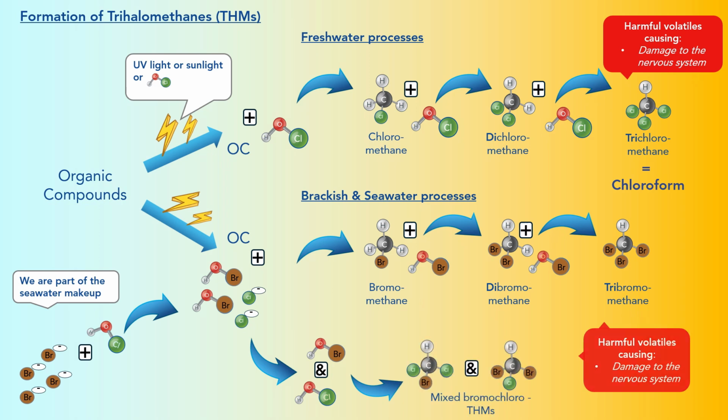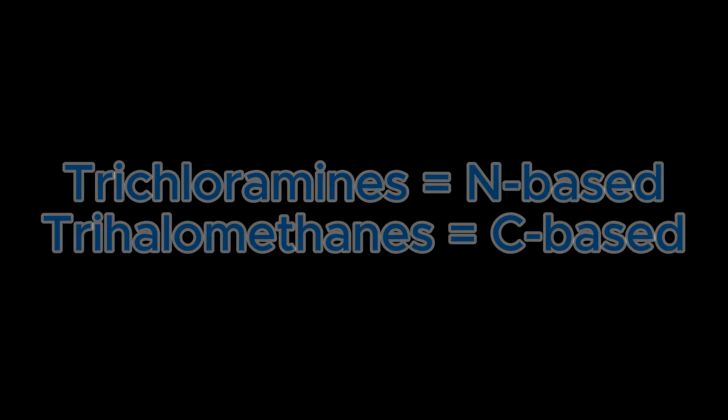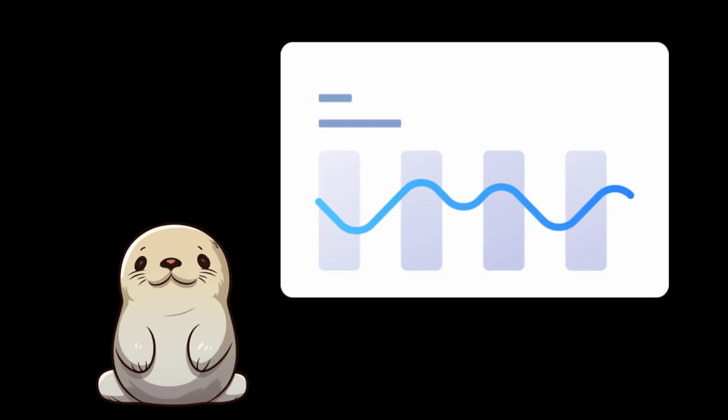Can you give us a key takeaway, Mike? Sure, if I understood you correctly, trichloramines are nitrogen-based reactions, while trihalomethanes are carbon-based reactions. Both are reduced with the increased removal of particulate matter. Great. Laura, do you have a good case study to support what we've discussed so far?